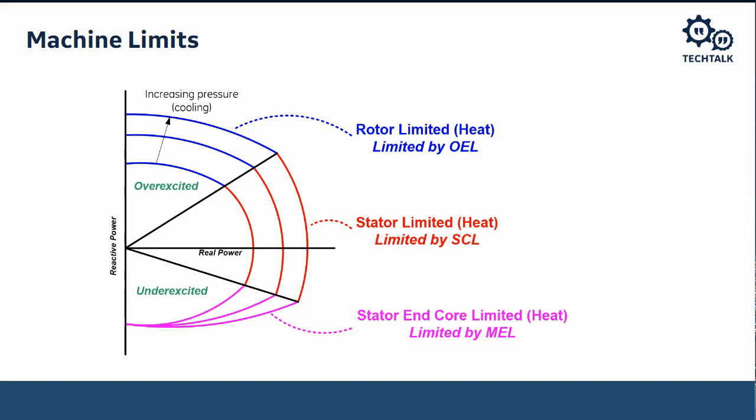But that's not what I'm seeing at all. Since the voltage and the current are in the opposite direction, instead of being along the real power axis, I'm to the left of the origin. It looks like I am consuming real power from the power system, and I'm underexcited. It's as if the generator is acting as an induction motor and drawing real power and vars from the power system. And we know it's not acting that way.